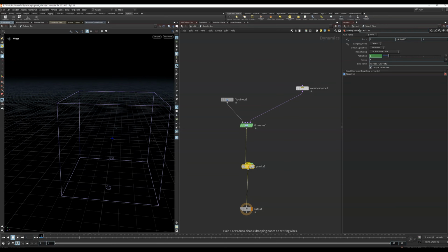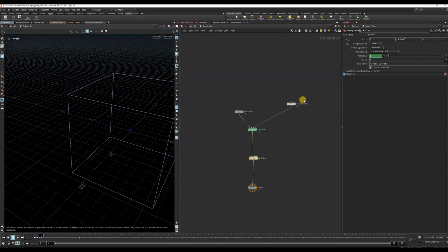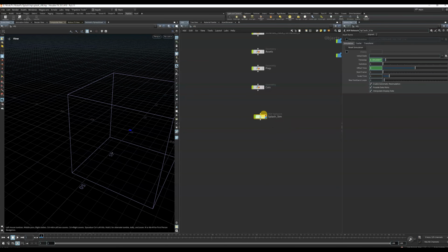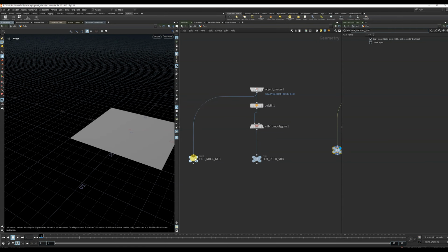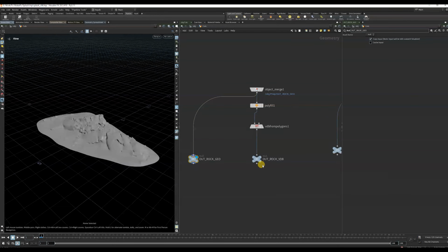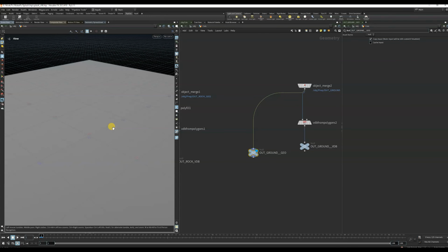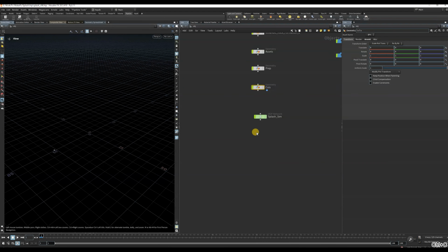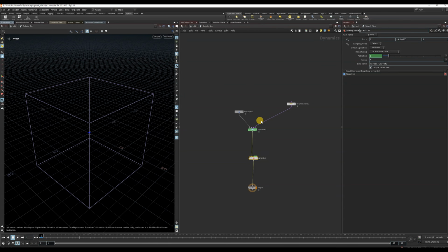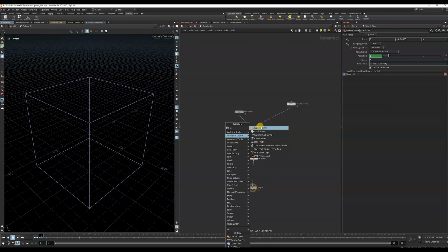Okay, so we call the static object the collision object. First for the collision object we go here. So this is our collision object. This is the rock, and this is the rock one, and this is for our ground one. Okay, so first I just call this rock one. So just select and copy, control C, and in the splash sim, take a static object.